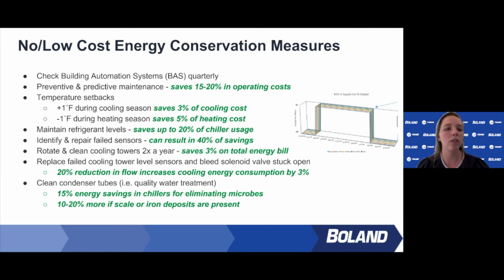Just changing your set points by a degree can help you save money on your cooling and heating costs. Another example is having your condenser tubes cleaned. This will regularly make the water cleaner and reduce excess energy.